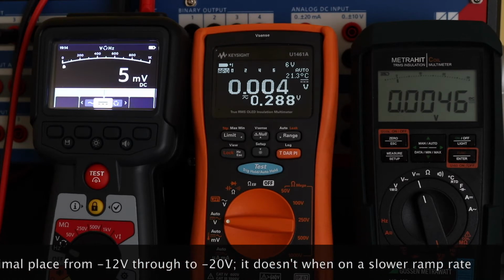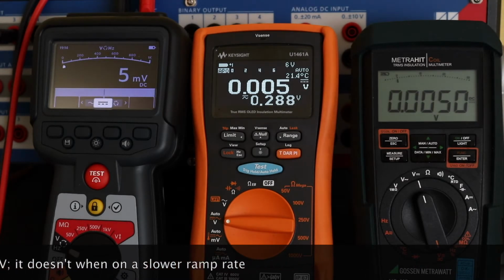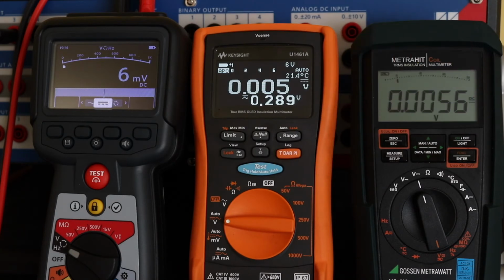I will put the results up in plots for all of the measurements that I've made. Accuracy wise, there doesn't appear to be any issues with the instruments. There's a bit of an issue over the speed at which the MTR105 responds, but on occasion for some of the measurements on some of the ranges you have a similar issue with the MetraHit. So the U1461A seems to have a better voltage measurement facility across the board.